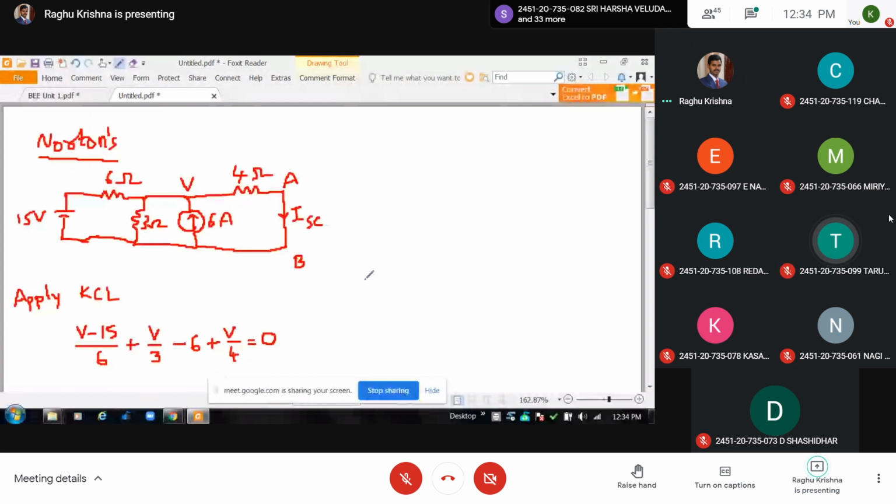Yes, sir. Okay. So here, the same problem I am using Norton's theorem. In Norton's theorem, I replaced the 11 ohms with a short circuit. So I short circuited the terminals A and B and am finding the short circuit current. For that, I am using KCL.